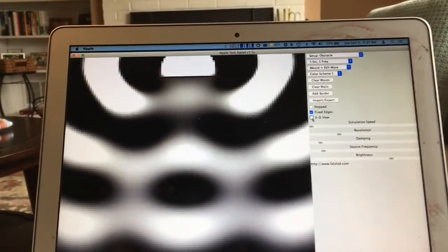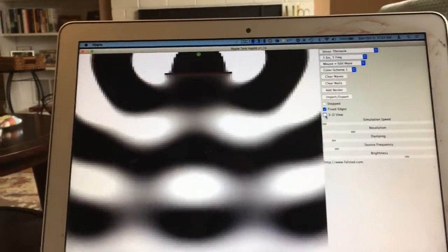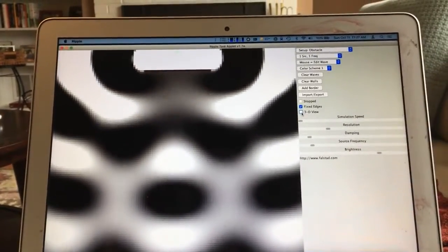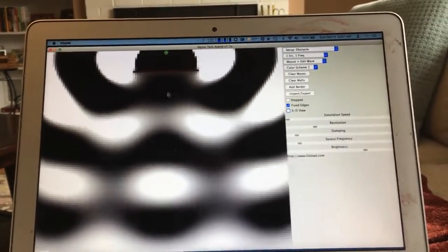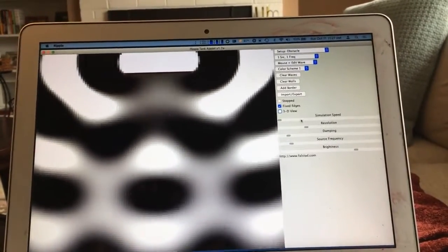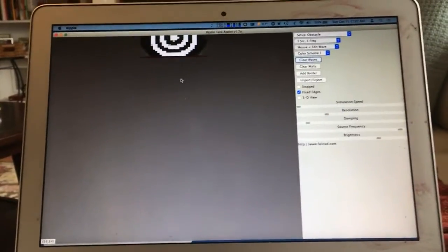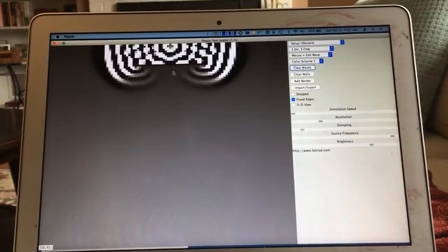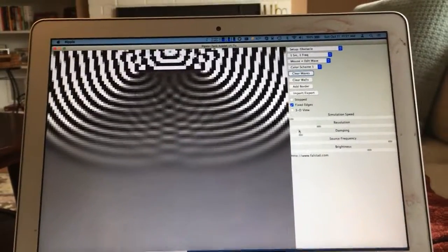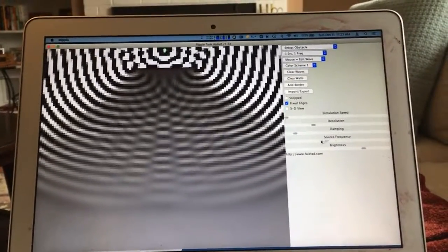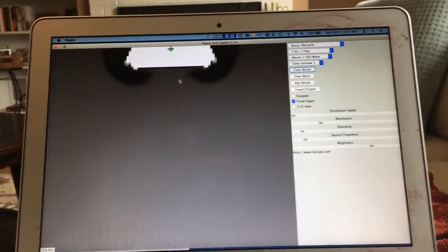For example, low frequency sounds running into maybe a column in an auditorium, or if you have a noise barrier along a highway. Suppose you have a busy highway here and you want to build a house over here and you put a wall in the middle, then very high frequency sound from the highway will be pretty effectively blocked, and you have a nice shadow region here where you don't have to listen to the highway noise. But if there's really low frequency highway noise, maybe the rumbling of a truck going by, then that is much more difficult to block because it will diffract around this barrier.